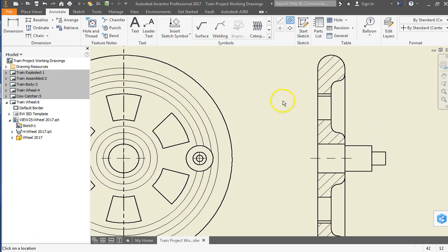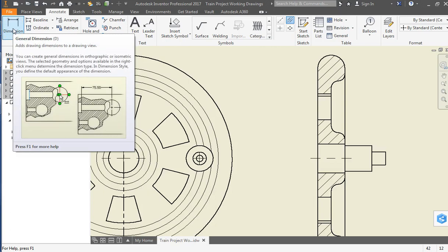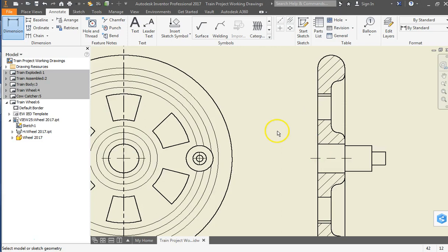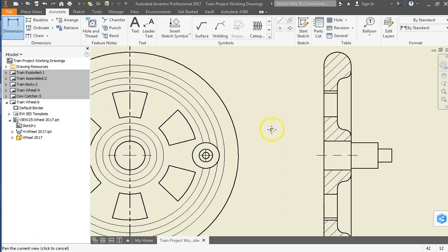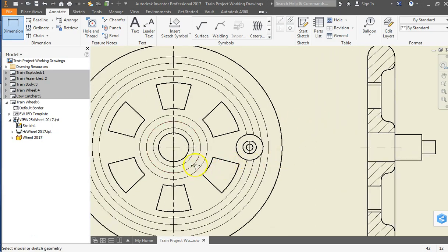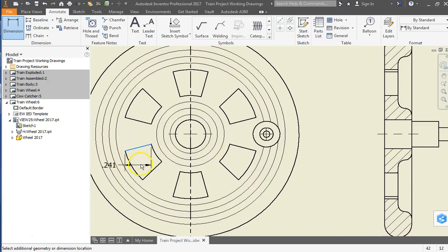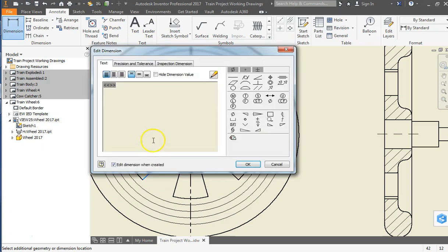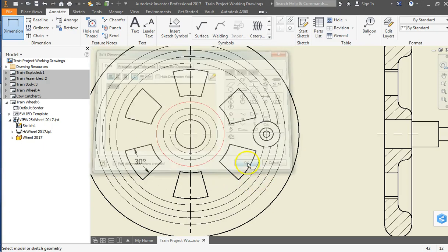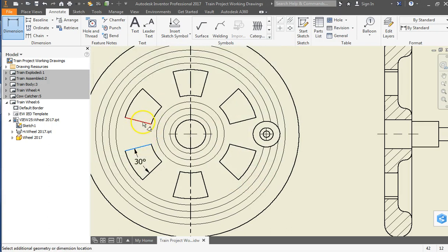Okay. From there, I've used my dimensioning tool to dimension heights and radii for the fillets and the arcs. I have used it to dimension angles. If you choose two lines that are not parallel, you can get the degrees of separation, like here. We uncheck that. And I might want to know the angle between the gap of those holes.